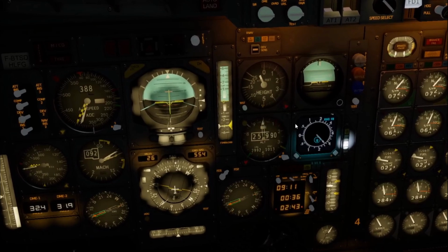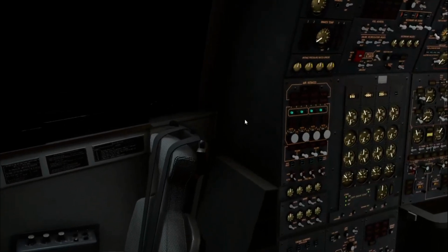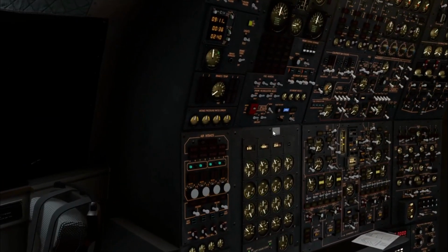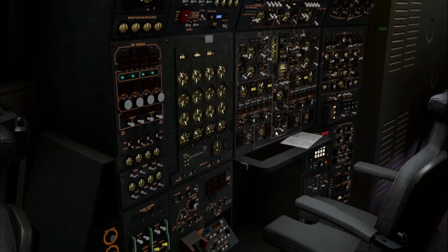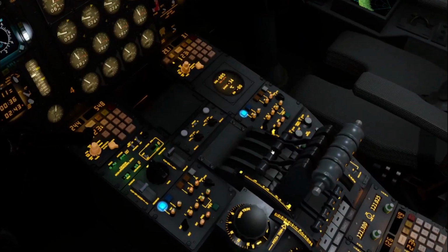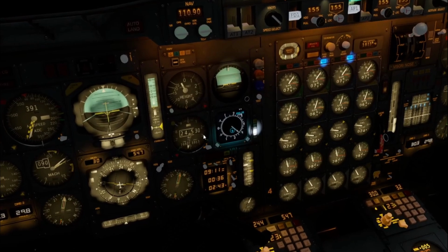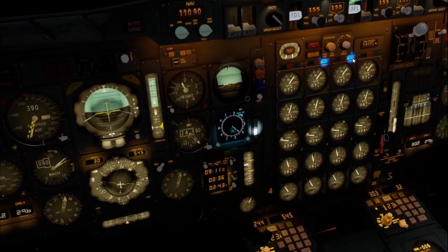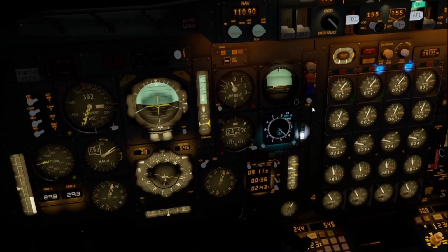So we're getting faster and faster. Still, we are too fast, and we can use something which is called in-flight reversers. So we will do this. I'll switch off transfer, and there is a throttle at idle. You may use reversers. They should slow down the aircraft. And you can see there are reversers. Only 2 of them work.